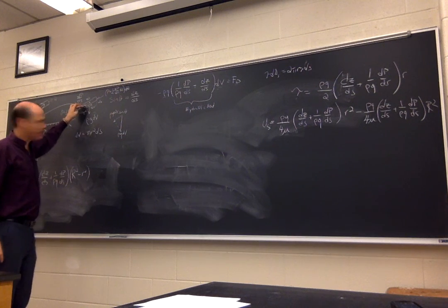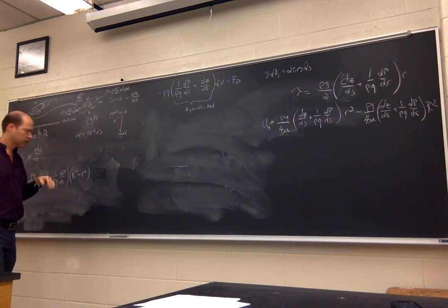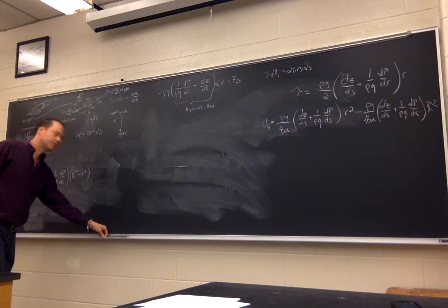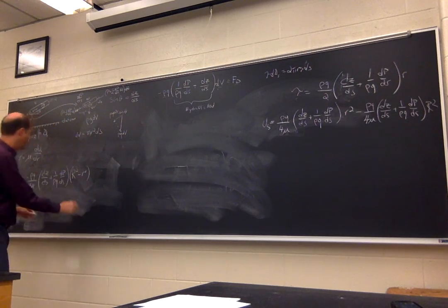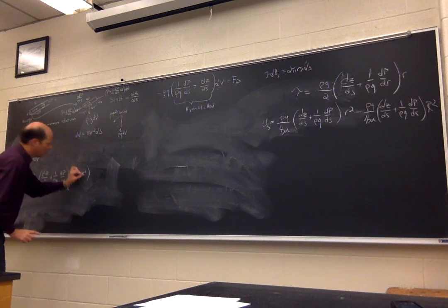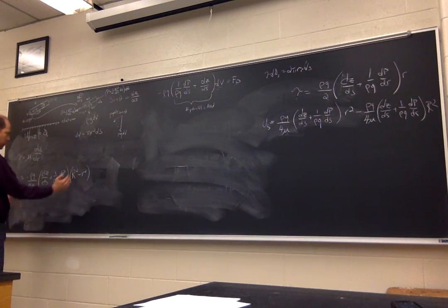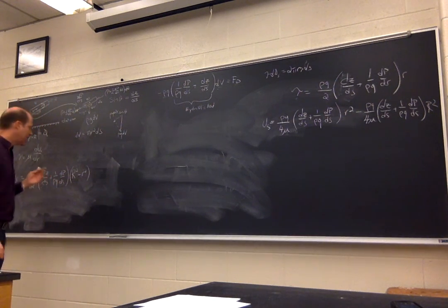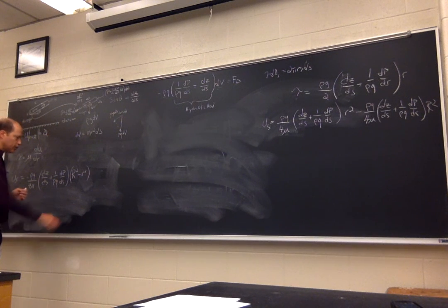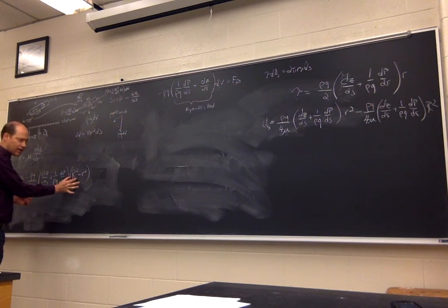At little r equals 0, that's going to be the maximum velocity, so the maximum velocity would be this equation where little r goes to 0. And the velocity at any point in that pipe is related to the size of that pipe and the position in there that I'm making my measurement.